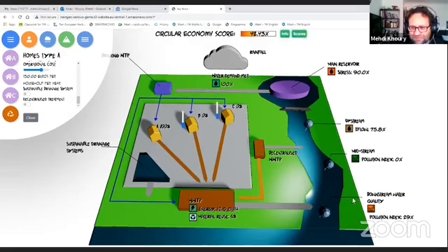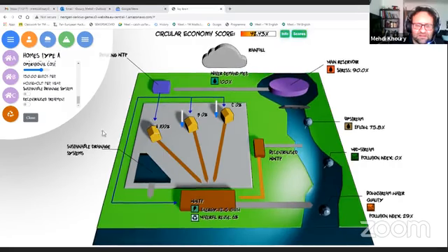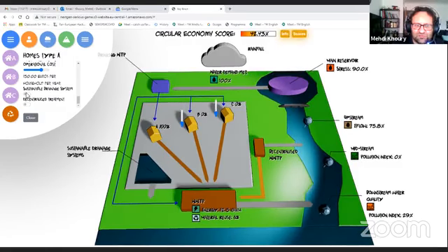And that's what results in a CSO event, an untreated discharge. But if you connect the houses to a sustainable drainage system, which is basically a basin that can absorb some of this rainfall water, then, if I click on it, you see it will minimize the pollution at a lower cost than trying to rebuild infrastructures.